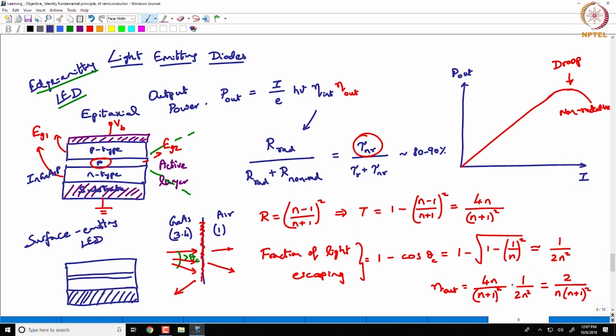So, you can use it as an electrode, but at the top what you would have is actually an electrode that is like a ring type of electrode. So, looking from the side it will look like this, but looking from the top it will look like a ring, and in this case the emission will happen like this. So, it will emit from the surface of the LED.